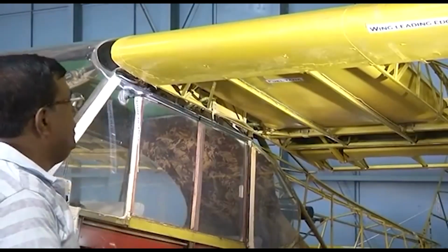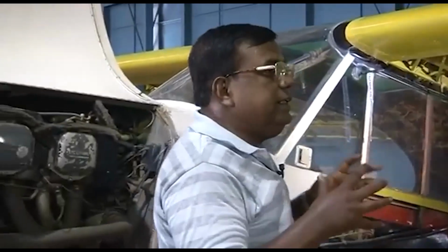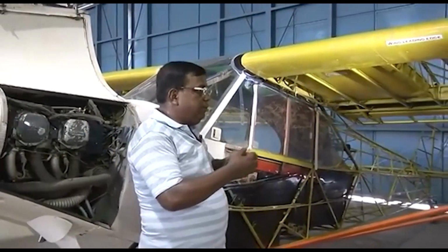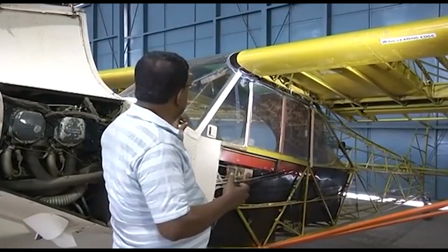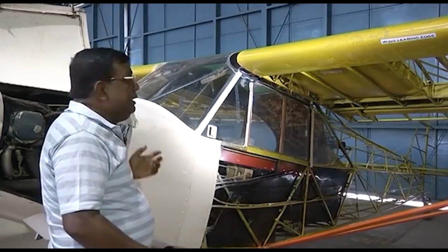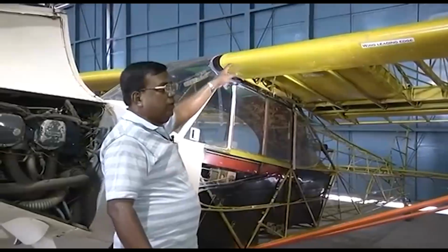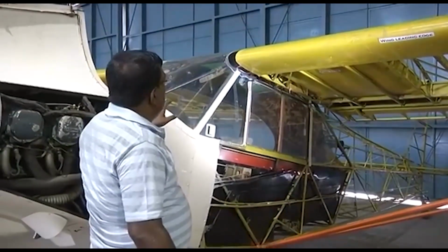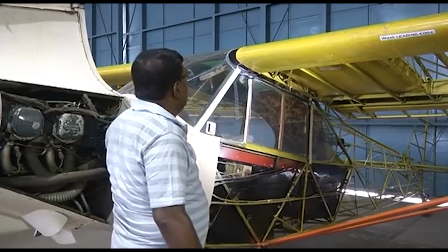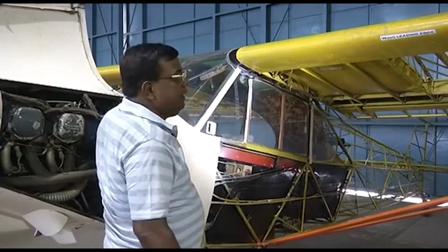The most important part is, please understand that fuel has to go to the engine, and the engine has a driving pump, and that pump is used to pull the fuel and put it inside the engine. So all the engines will have their own driving pump, which we call the driving fuel pump. And since it's a high wing, the fuel from here to the engine comes by simple gravity drop. Now the question is whether we draw fuel all the time from both tanks, or we can selectively take fuel from one tank, and once that tank is over, I can take the other tank.